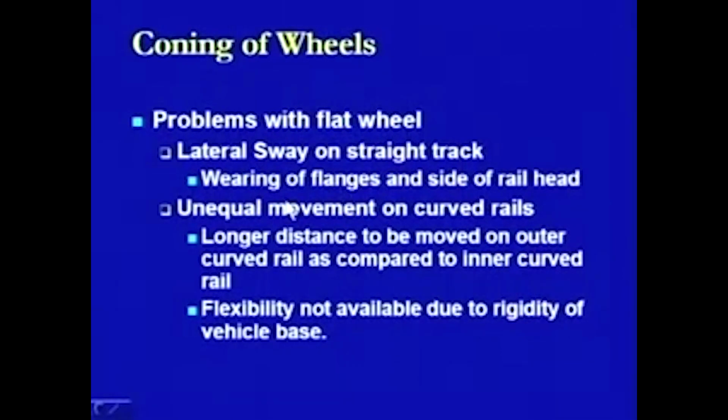As soon as there is a lateral sway, it will create a condition of the wearing of the flanges. At the same time, it will also create the wearing of the side of the rail heads. So this is one of the drawbacks of the flat wheels.